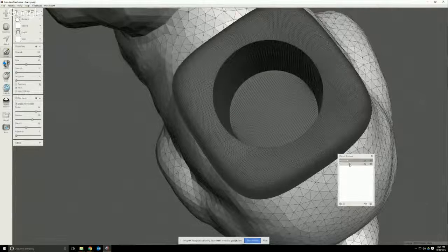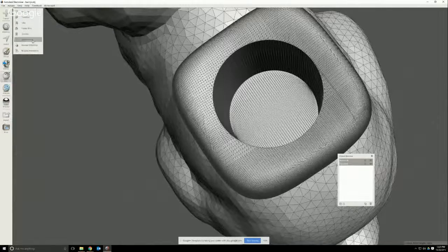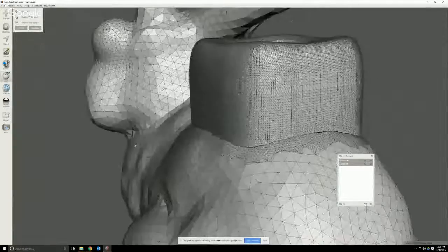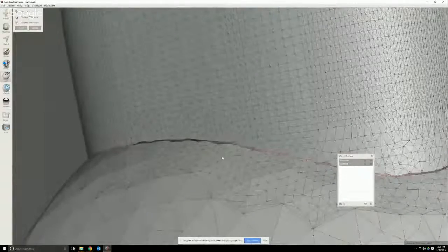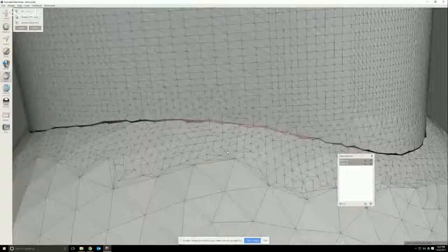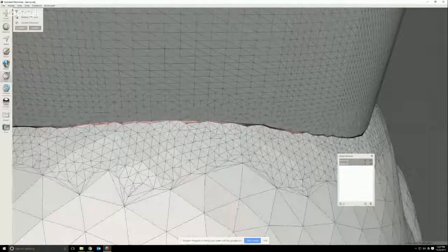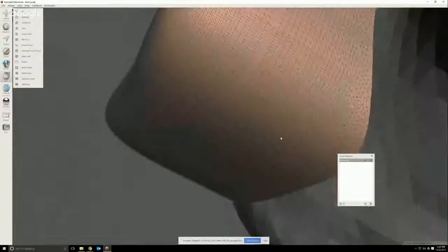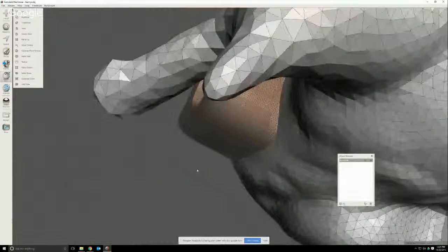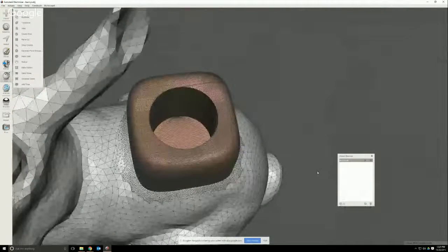So now I have the bunny clicked. I'm going to hold down Shift, click on the candle, and do a Boolean union. It kind of shows that there's a cut right here, but that's okay because it'll close that cut up later. Click Accept. Meshmixer will think about it for a second and create a nice edge. So now you see we have one object with that candle holder beautifully in the bottom.